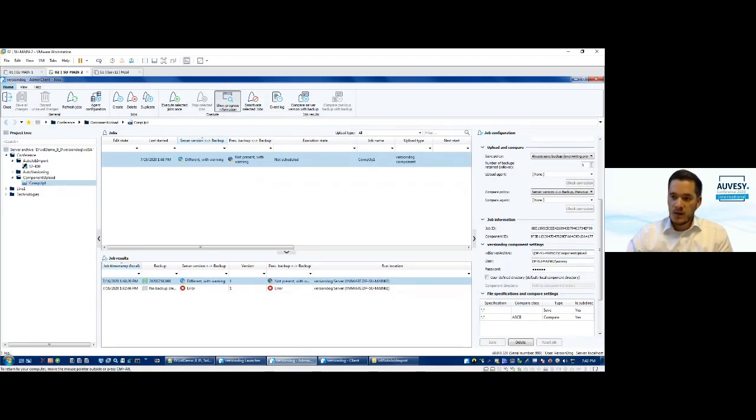Here you have to set up the network path to the shared VD server archive and the credentials with which you want to access this network path. It's necessary that this user has read and write rights to the network share, so that we can copy the data from the share to our versiondog system.